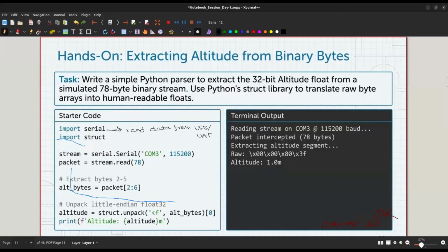UART helps decode the universal format of data acceptance via your ports. In Windows, you have your ports like COM3. In Linux, you have ports like /dev/ttyACM0. It's recognized that way. Similarly, in simple terms, when you plug your phone into your laptop via USB, it will say your device X has appeared. So device X is basically the name of the USB when you connect it with something like an Uno or Arduino.